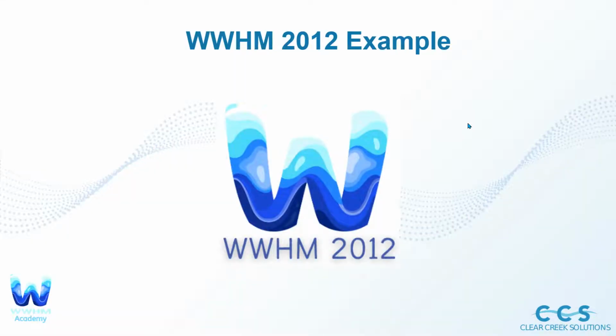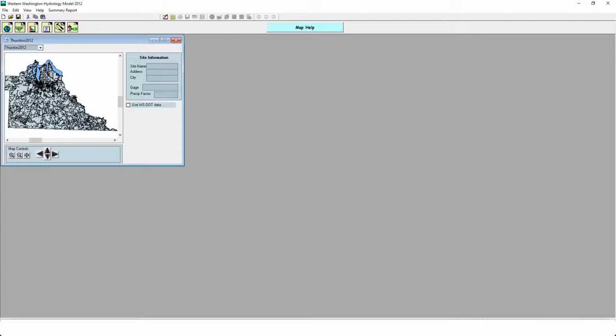So here's what we're going to do. We're going to go into WWHM 2012. I'm going to show you how this works in a continuous simulation software. So this is WWHM 2012. And what we do in this software is we select a location, a project location on the map. And this determines our precipitation data and our factors.